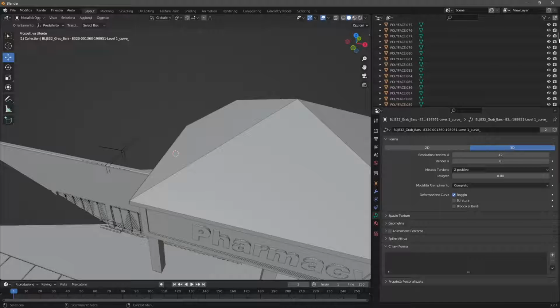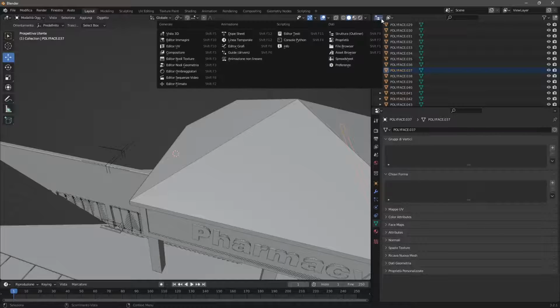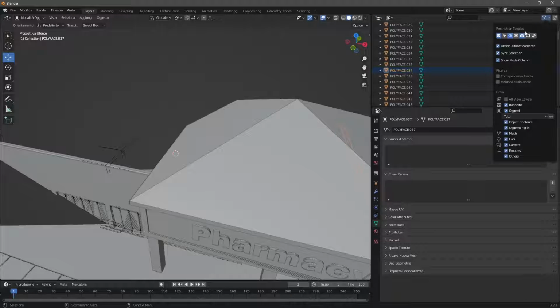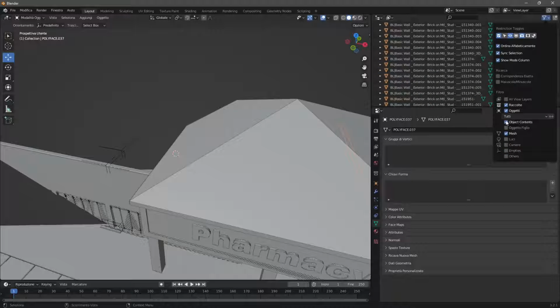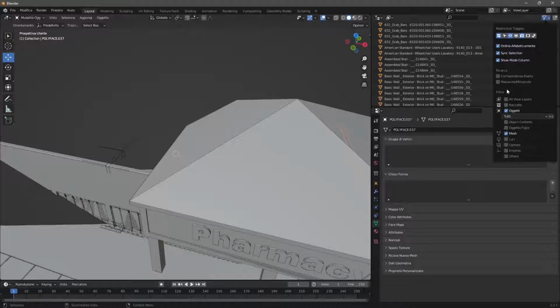And you can see the complexity of these. This is because these are coming from a BIM application. So they are a little bit more complex and divided into many different phases and families and types and things. Now with the triangle, these are all meshes. So if you want to work only with the 3D, well, we can filter these. There's the filter right here. So we can filter and just get rid of everything that is not a 3D object. So it's going to be object and mesh.